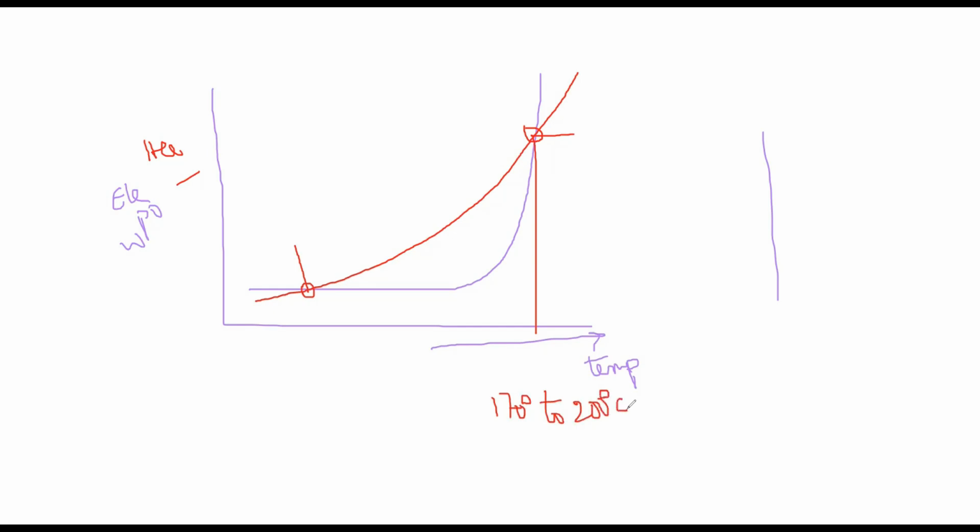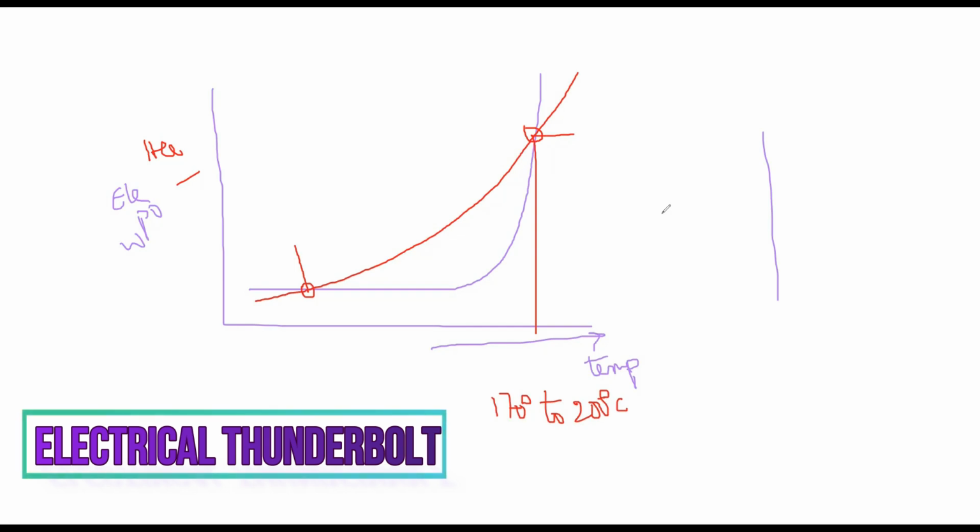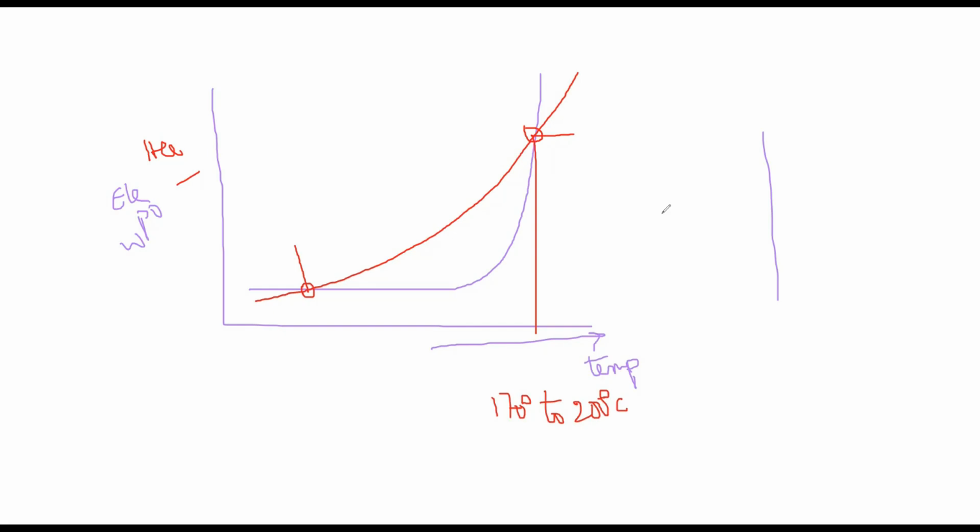Beyond this, cooling is not possible here, and the metal oxide resistors will burn out. So whatever energy you pass through, each metal oxide resistor faces that energy and should be capable of handling it. That is also one more factor we have to consider when sizing the lightning arrestor.